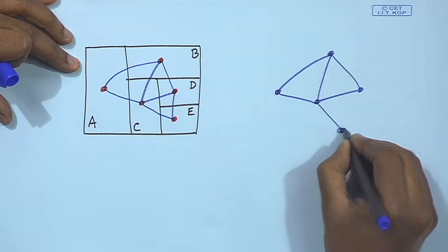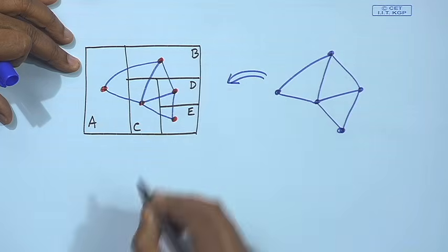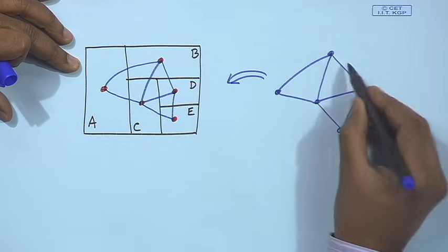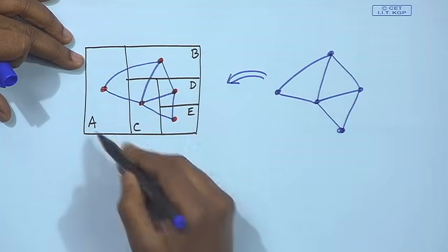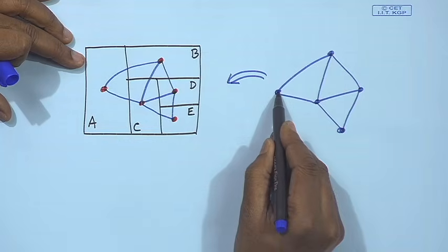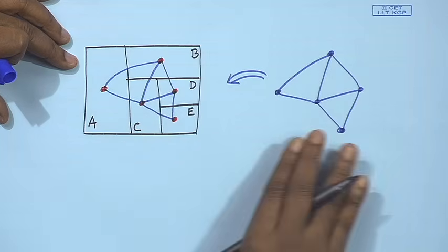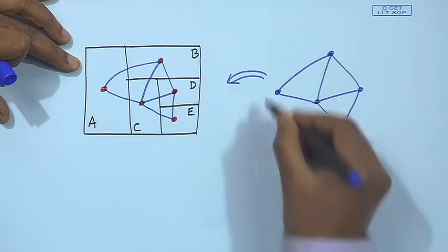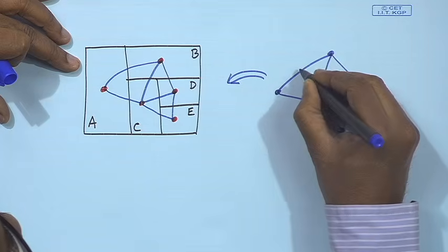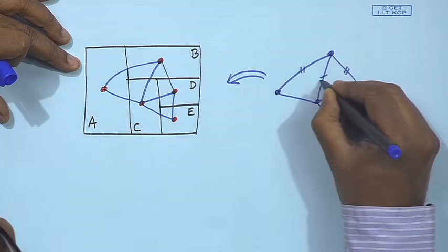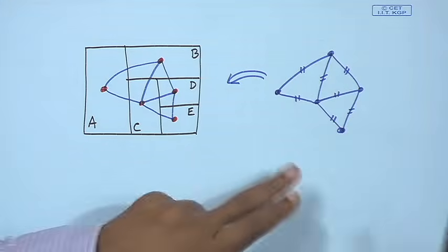So, the graph will be like this. Then from this graph you will have to translate it into a floor plan. Now, it is not difficult to do it. Given a planar graph like this, you can convert it with a rectangular dual, replacing every vertex by a rectangular region, and you will be getting the floor plan like this. Now, this is the output of the partitioning problem, where each vertex will indicate the blocks and the edges will indicate the number of connections between them, the weights of the edges, that is how strongly they are connected. Okay. This is the idea behind rectangular duality.